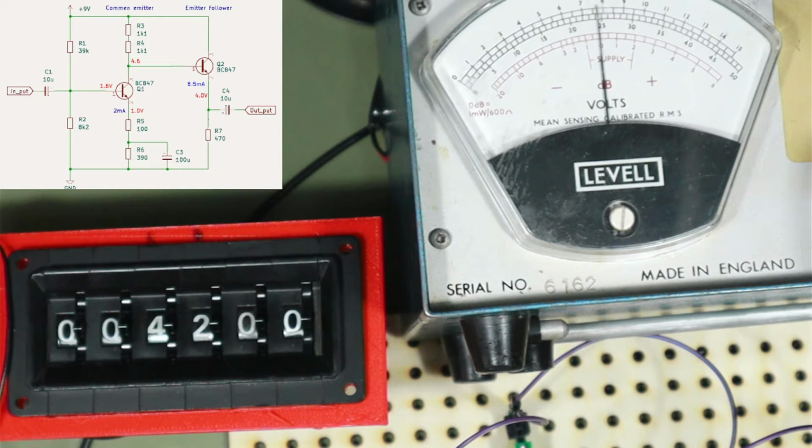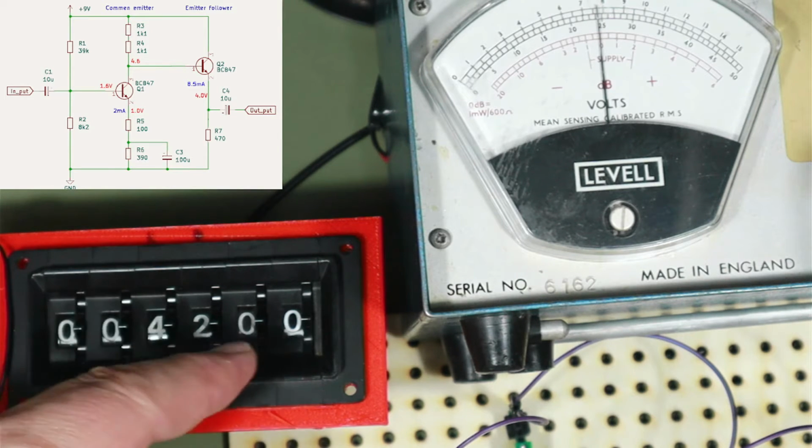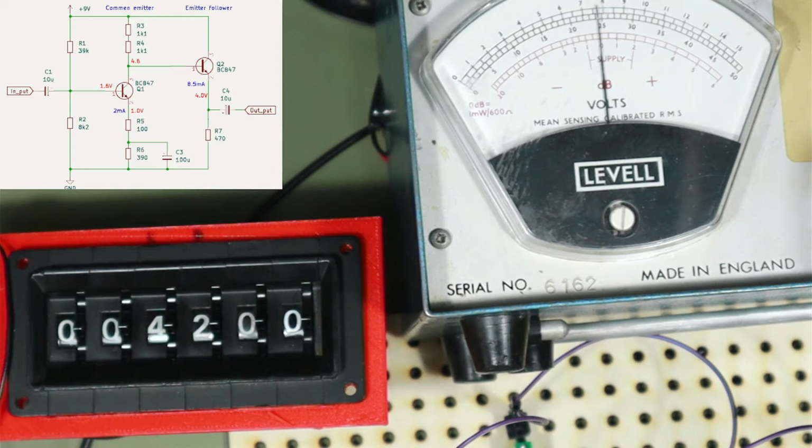It's going to be a bit different because obviously this value is going to affect the level of the oscillator going in, and if you want to do it properly, you want 2 meters so that you can keep the input voltage constant at say 1 volt, and then you adjust this until the reading here equals half a volt, and then you've got the true input impedance. But this is close enough. It's somewhere around 4.2K, and I think I calculated it as 4.7.